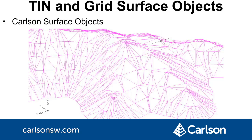The Draw Triangulation and Grid Surface commands have a new option to create a Carlson surface object instead of drawing as 3D faces. These are the first custom objects that we have created. The main advantage of the custom object is performance with large surfaces. Besides viewing the surface in the drawing, you can also snap to the surface.